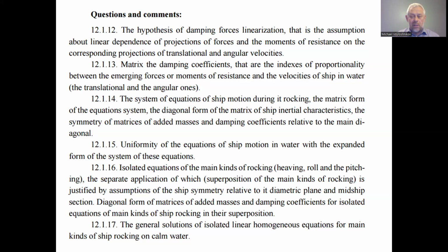And for these matrices of the unit displacement, we say so, but actually this is the displacement under the action of unit forces in the cut-off connections when making the main statically determinate system out of the assigned statically indeterminate mechanical system. But this system of displacements and action of unit forces looks very much like the system of added masses in determination of the ship motion equations, and like the matrices of the damping coefficients.